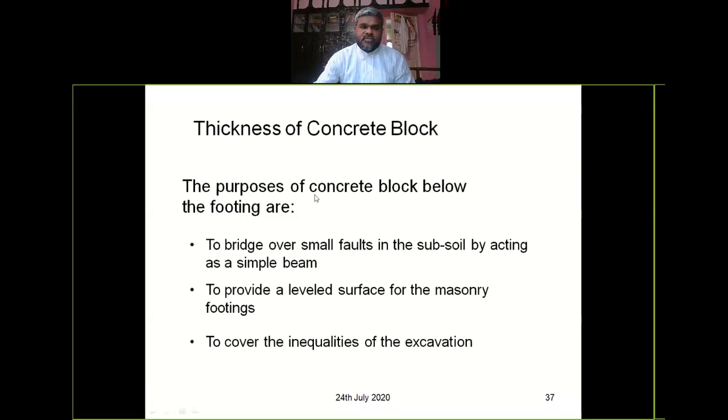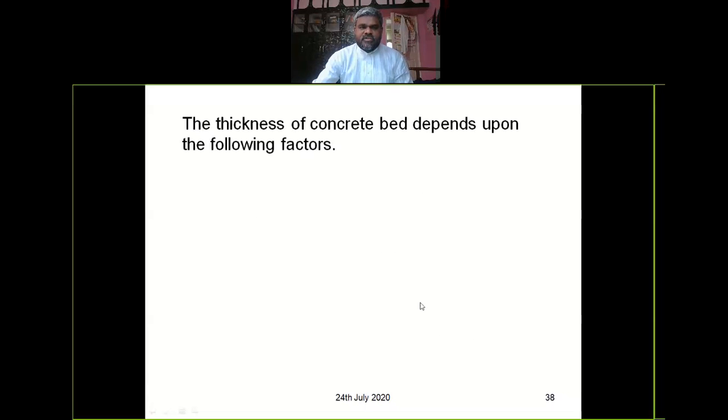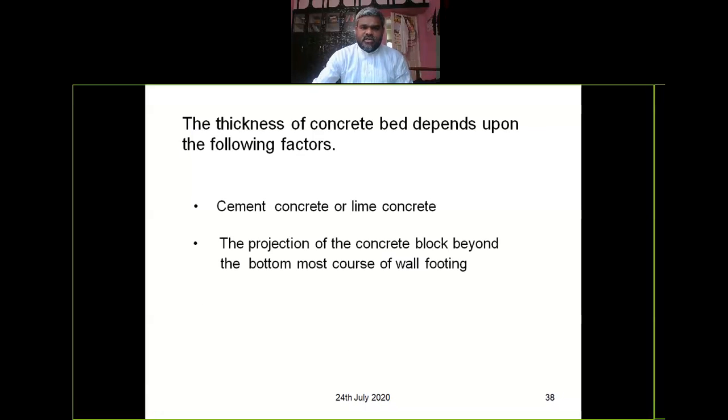Next is the thickness of concrete block. The purposes of the concrete block below the footing are to bridge over small faults in the subsoil by acting as a simple beam, and to provide a leveled surface for the masonry footings to cover inequalities of the excavation. The thickness of the concrete bed depends upon the following factors: cement concrete or lime concrete,